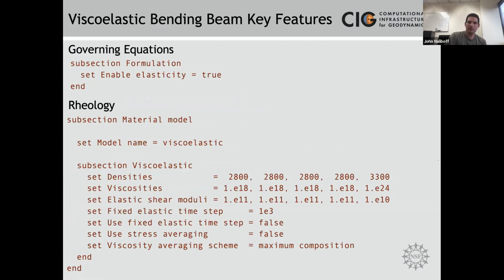So in terms of the rheology and the governing equations, in the formulation subsection, if you're using viscoelasticity, you do need to set enable elasticity equals true. In the material model section, in this case, we're using the viscoelastic material model. And then here are the values you need to prescribe. We're assigning a density for all the fields. So then these first 3 are stresses. Then this is